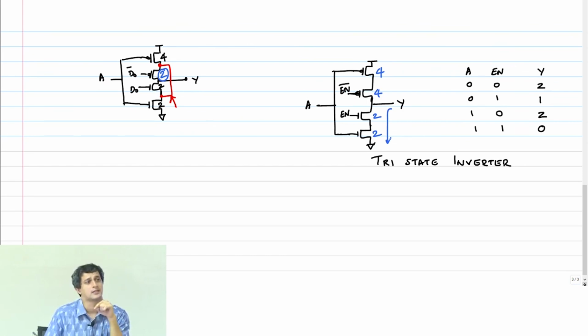Now in my other case, because I have this red parallel connection here, both the NMOS and PMOS of the transmission gate will conduct together. Though the NMOS will be slower, it will conduct only up to VDD minus VT, but for most of the time, it is going to conduct. So in some sense, they are both in parallel and therefore you can reduce the size slightly. Instead of 2244, you are able to make it 2224. That's all.